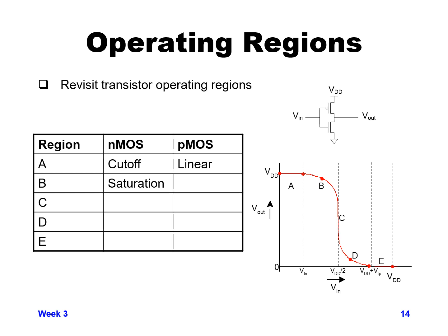The input voltage is greater than the threshold voltage, and the gate voltage is greater than threshold voltage, and the drain voltage is really pretty high. It's all the way near VDD, so the drain voltage is much greater than VGS minus VT.